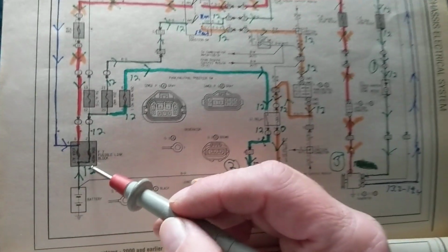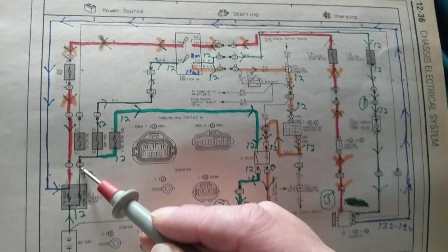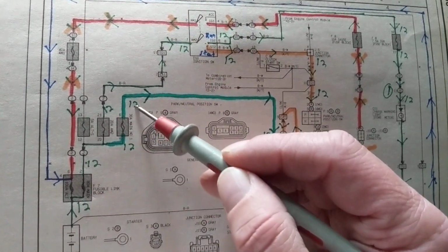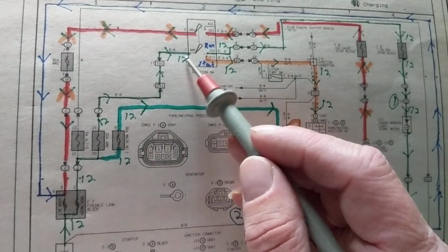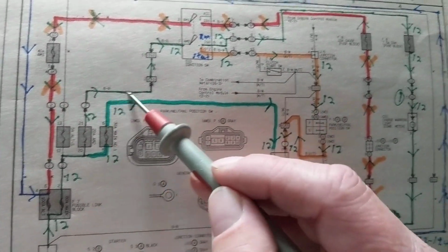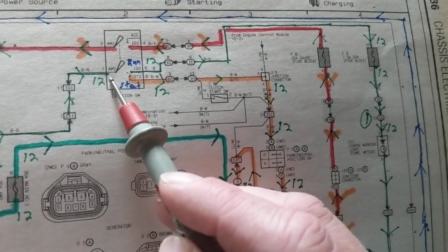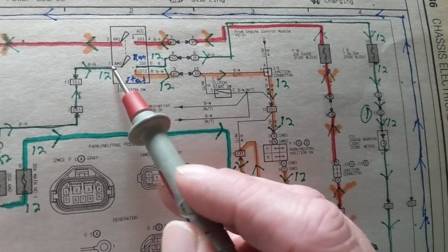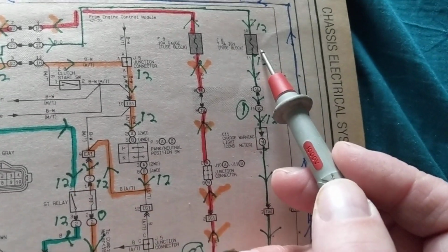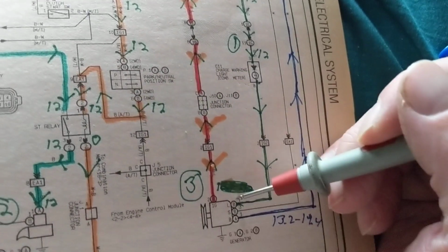But let's see. We're going to call this a fuse instead of a fusible link. One fuse. Remember, we have to get to here. One fuse. Do we go here? No. We have to go this way. We're concentrating on this point. Here. Another fuse. Through where? Through the ignition switch. In which position? The start position, in the run position. Here. Here. Here. Another fuse. Three fuses. Three protection devices to protect this alternator.